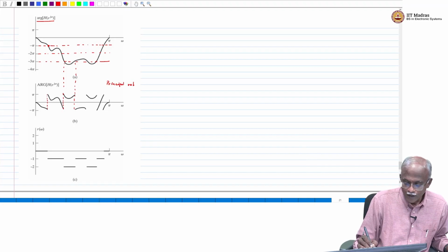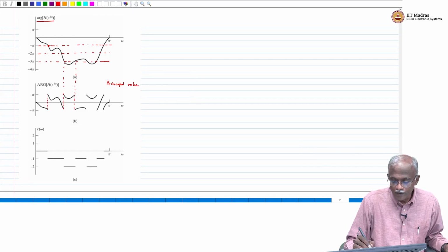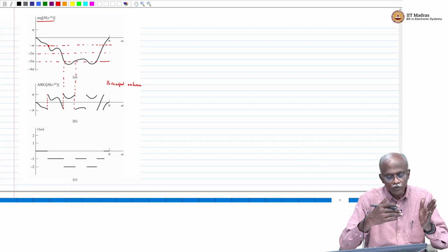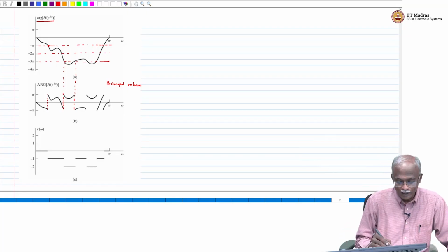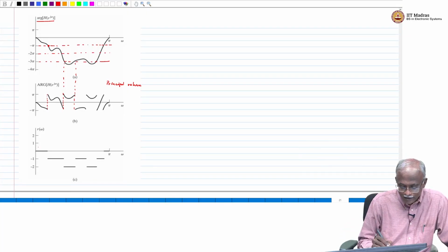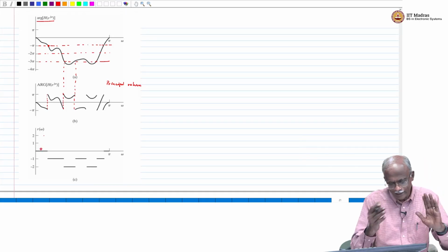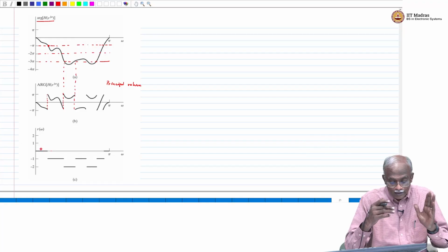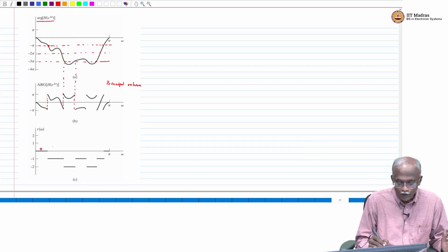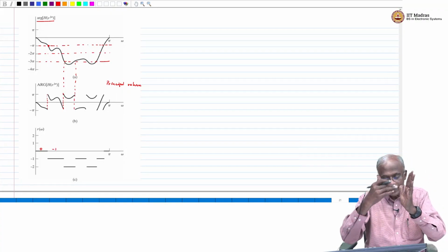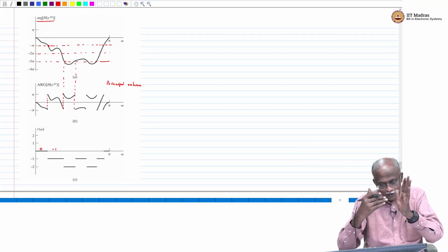Now how are the principal value and the true phase related? You always have to add or subtract a multiple of 2 pi. So in the first region here, r of omega is equal to 0. That means you don't have to add. Whatever is the actual phase is the same as the principal value. Now in the second section, you subtract minus 1 times 2 pi from every phase value that you see, then you will get the second part.